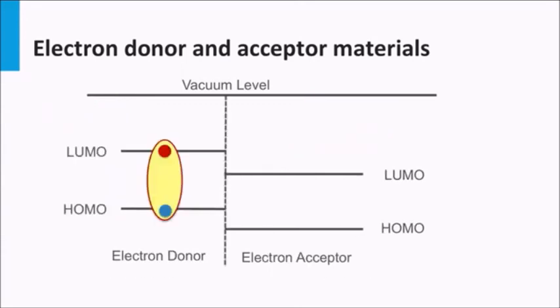Another important aspect of exciting charge carriers in organic materials is that it differs from that of inorganic semiconductor materials discussed so far. In inorganic semiconductors, we can excite an electron from the valence band to the conduction band, leaving a hole in the valence band. In a semiconductor, such an electron-hole pair is weakly bound and both entities are easily separated and can diffuse away from each other. In organic materials, this is not the case.